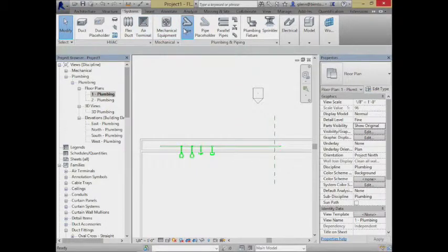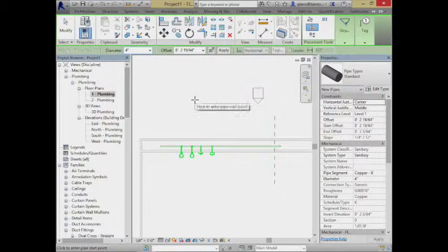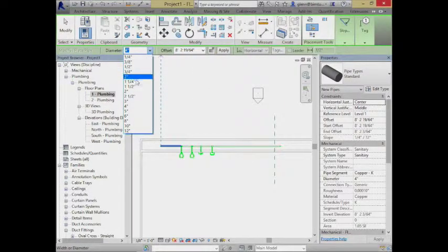Let me go through and run another pipe in here. In this case, I want to run a cold water pipe that's going to service a lot of these fixtures. I'll put it also in parallel back in that little mechanical chase. In terms of its diameter, I'm guessing a 2-inch pipe would probably be fine. Again, we can get Revit to give us some guidance about sizing this based on the actual load, how many fixture units need to be fed by the pipe.